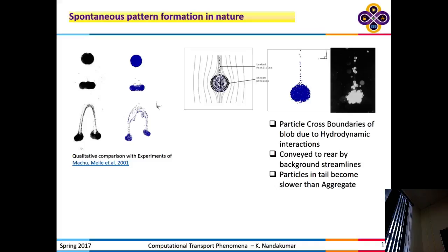It will sink, it will settle, right? Why? Because of the forces acting on it. So there is weight, gravity is pulling it, and then there is of course buoyancy because it is submerged in a liquid, and it reaches the terminal settling velocity. There is a drag the liquid exerts on the particle as it moves, and these three are in balance, so it reaches the terminal settling velocity. This was known very long time ago, Stokes solution, right, to the Navier-Stokes equation.